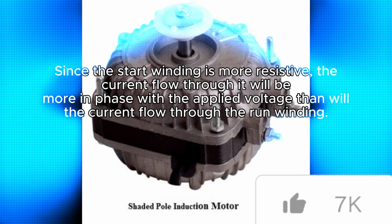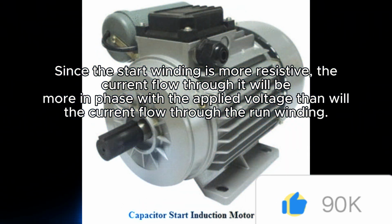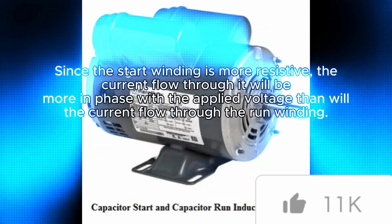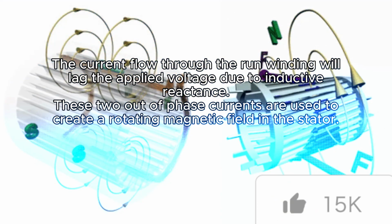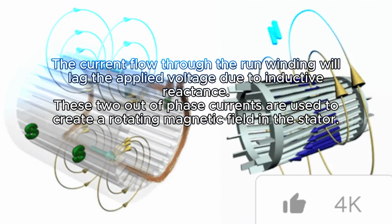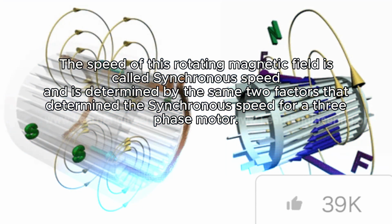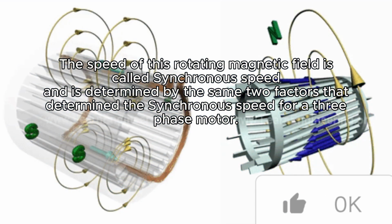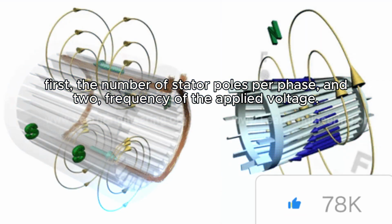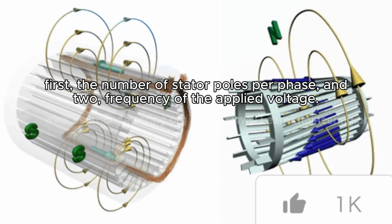Since the start winding is more resistive, the current flow through it will be more in phase with the applied voltage than will the current flow through the run winding. The current flow through the run winding will lag the applied voltage due to inductive reactance. These two out-of-phase currents are used to create a rotating magnetic field in the stator. The speed of this rotating magnetic field is called synchronous speed and is determined by the same two factors that determine the synchronous speed for a three-phase motor: first, the number of stator poles per phase, and second, the frequency of the applied voltage.